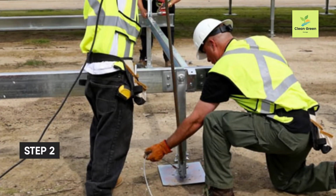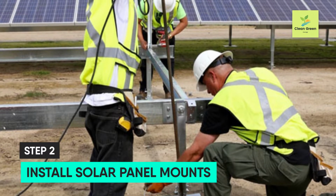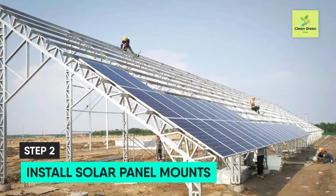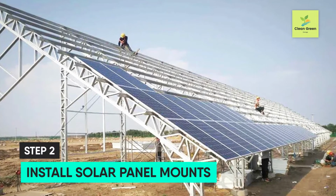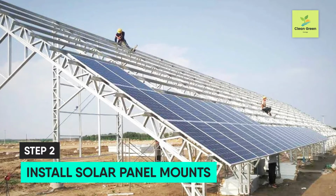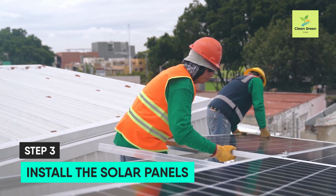The second step, install solar panel mounts. Then, the solar panel mounting system has to be set up. This will support the base of the solar panels. The whole mounting structure must be tilted and have an angle between 18 to 36 degrees and have maximum sunlight exposure.